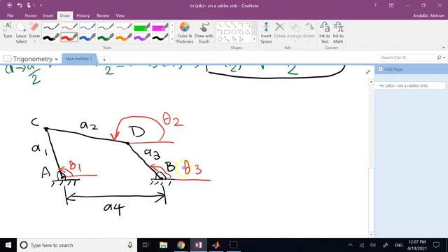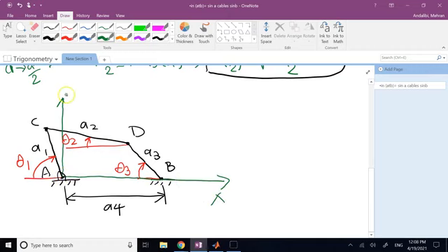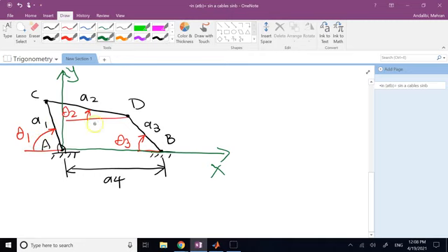And then if I want to, I can use these angles and find what I need to find, or if I want, I can measure every angle with respect to the negative side to avoid a bunch of conversions. So if I want, for example, I can call this angle theta 3, make life easier. I can make this angle theta 2, and I can make this angle theta 1. This will basically make my life probably a little bit easier when you come to derivations. So here you can set your coordinate origin anywhere that you want. Let's say I put it here right at pin A, and so this is my x-axis, this is my y-axis, and here if I give you angle theta 1, can you give me angles theta 2 and 3?